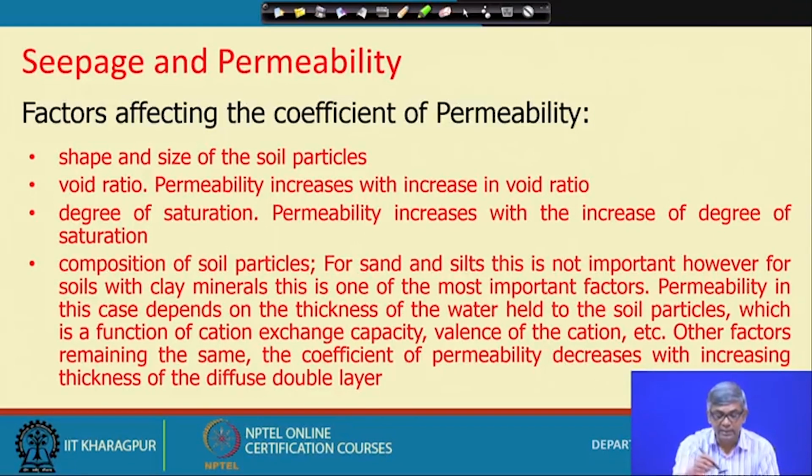For sand and silt, this is not important. However, for soils with clay mineral, this is one of the most important factors. Permeability in this case depends on the thickness of the water held to the soil particles, which is a function of cation exchange capacity. These are some theories, we will not be able to give much detail, but the only thing you can remember is that composition also is very important, particularly for fine soil.